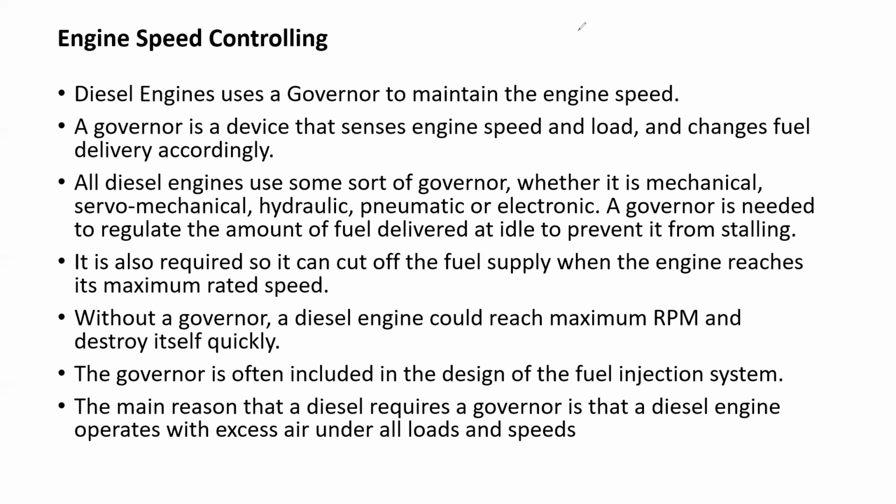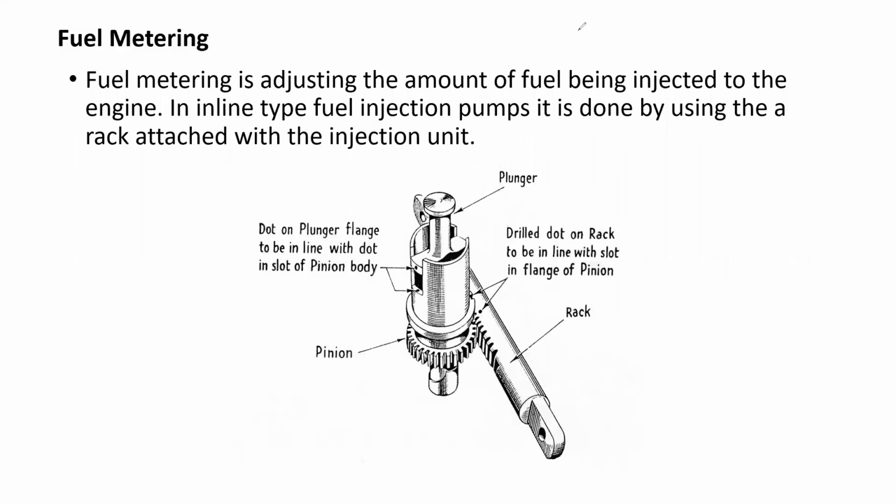That is a problem. So to control that, we have the governor, right? I told you there's a governor in this hand, and we have our pedal here. We press the pedal over here, and the engine has to go up to 2000 rpm, but it tries to go to 2100. As soon as it does, this governor interferes, pushes it back and reduces the fuel, right?